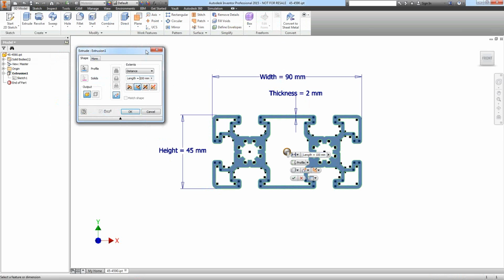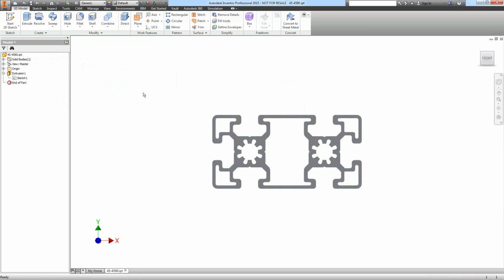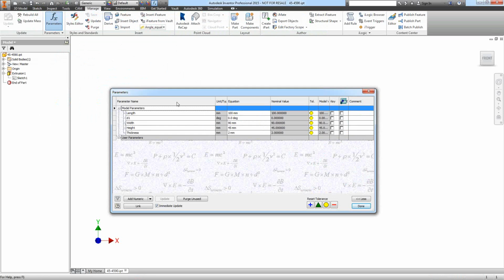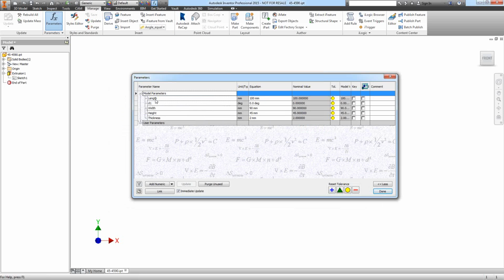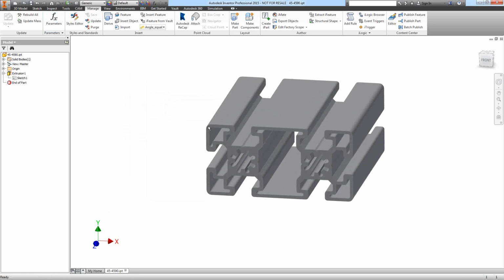So if you've never done this, use this process to name a parameter for it. Just to note, you can type in the name and then equals and then whatever value. And that can be easier, especially if it's a model that someone else created, than going to your parameters page and trying to figure out what D0 is and D1 and D2. You can go right there while you're editing and give them appropriate names. Okay, so I've got a few parameters to work with.